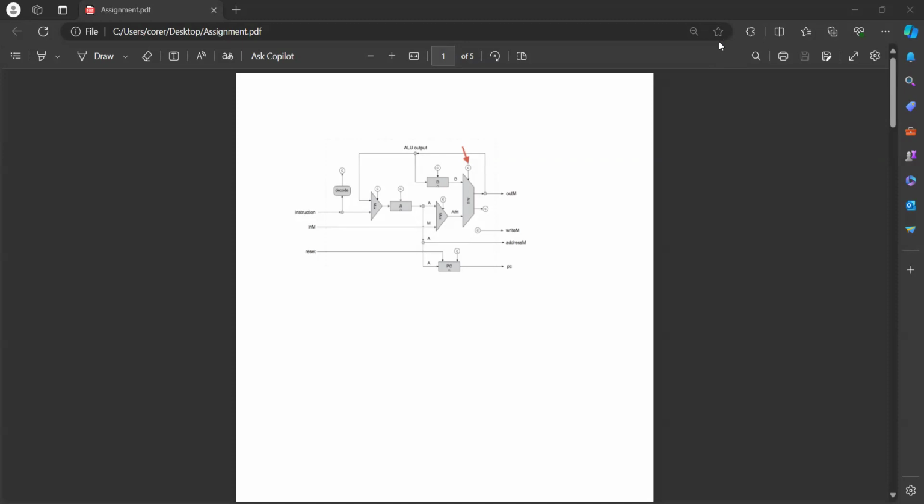In this first picture, the suggested architecture of the CPU, which I will use to describe and implement the HDL code for the CPU, is represented by this diagram. Many logic gates, such as the multiplexer, ALU, A register, D register, and many more, make up the CPU. In order to quickly identify the input and output pins of the CPU, let's start this clip by hiding all of the logic gates in the figure.